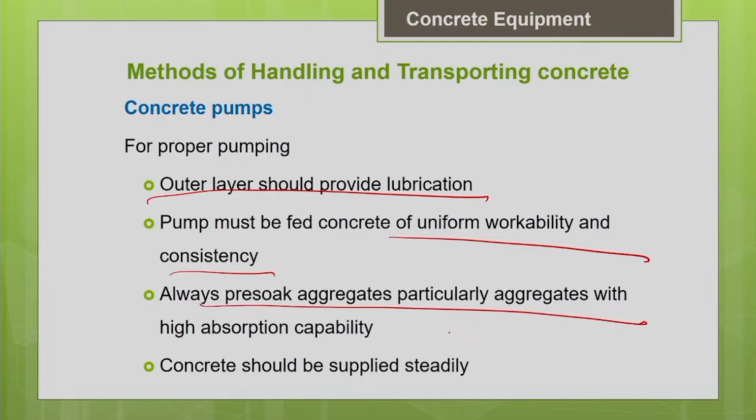So, what will happen is the workability or the pumpability of the concrete will get severely affected. So, in that particular case, before pumping you are supposed to do the pre-conditioning of the aggregates. That means you pre-soak the aggregates, so that they absorb the water well. After you put them in the concrete, they will not absorb your mixing water, and that will not affect your pumpability or the workability of your concrete. So, this kind of preconditioning is needed.